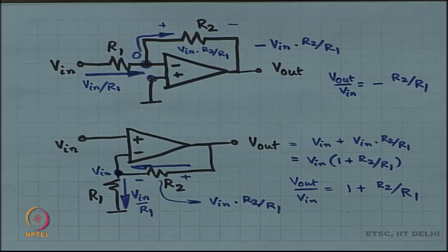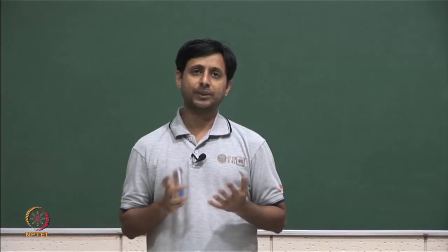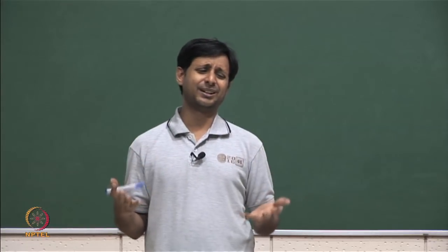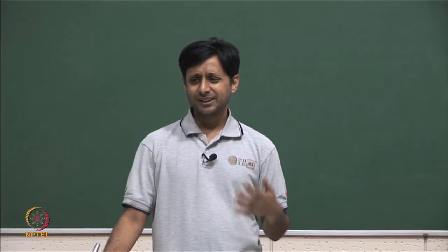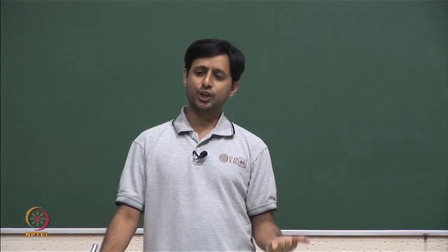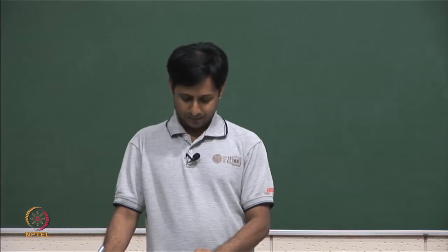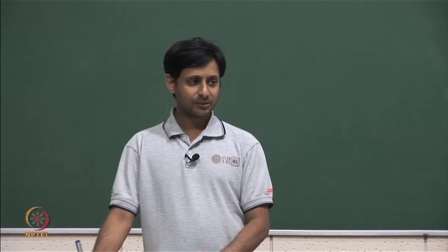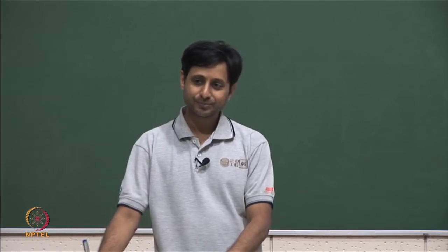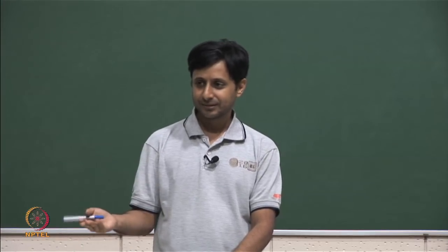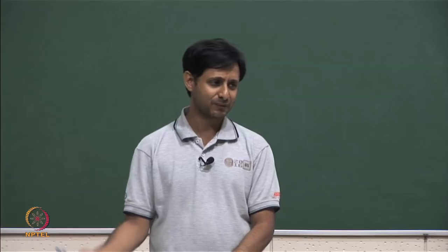Now, we have one important issue over here. This is what we were discussing in the last class. The issue that we have is that the op amp that we made is not really an op amp. What we made is an operational transconductance amplifier. We did not really make an op amp because its output impedance was large. Okay. So, the output node has got to be a drain of some MOSFET, right.